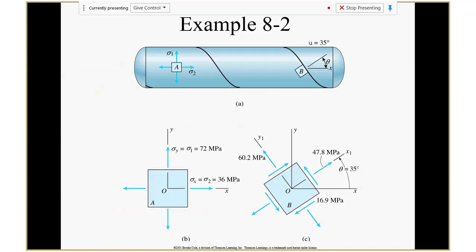Okay, so when built this way, then the issue will be, what's the theta? That's a line, right? That line you have a direction, theta direction. So what's the stress on that surface? Because if this one fails, most likely you will fail along that line. You're not welded strong enough. The glue, that would be one concern. So you want to know what's the stress along that line, right? Say we know the pressure inside, we know the diameter, we know the length, everything. Okay, how can we find the stress along that line?